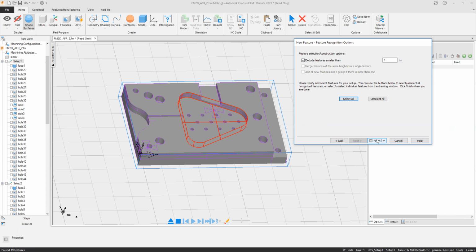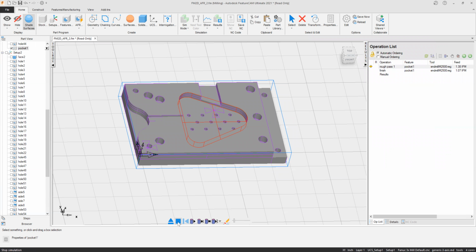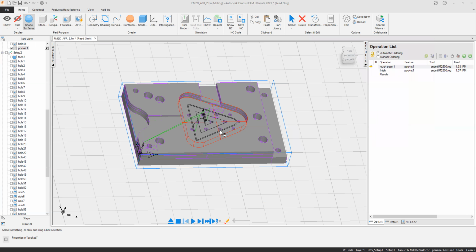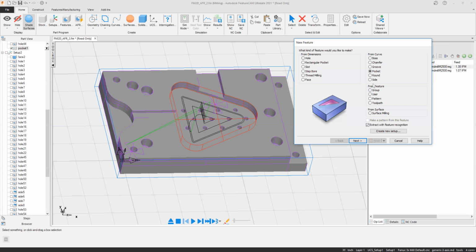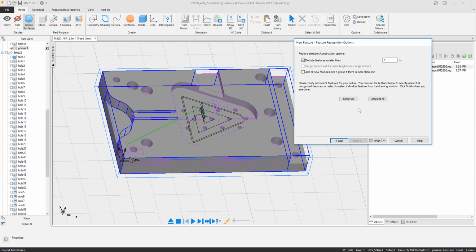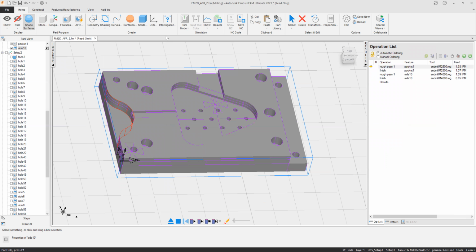Then you select it. Now it will do the toolpath only for this pocket. Okay, like that, if you also want to do the side, I can do it for the side. Okay, now you can see this is only the pocket toolpath, roughing and finishing is going to be generated. Like you can do particular pockets or a particular area you want to machine. Or now I want to do this side machining, then I can go to the side, then select. Whatever side I want, only this one, select only this one, then you can finish it. Now it will generate the toolpath only for this side.